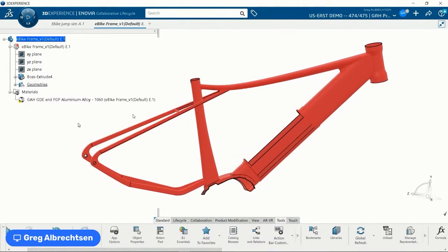But I want to do some things. Let's say I want to mid-surface this. I could do that in SolidWorks, but then I'm changing the SolidWorks geometry, and if I have some drawings and things like that, how's that going to affect my actual SolidWorks geometry? So when I think about preparing a part for simulation, I like to leave my original geometry alone. Let my SolidWorks geometry be my SolidWorks geometry, and now let's create some construction geometry for simulation.